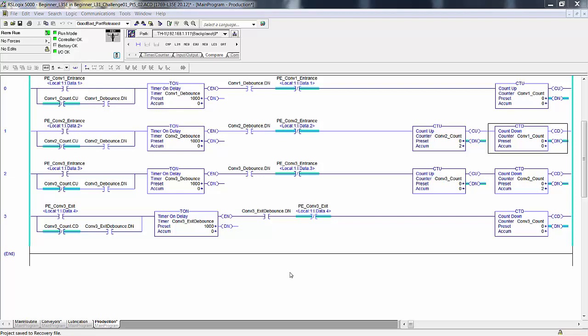It is not a good idea to start writing the controller program until this phase is completely finished, including and especially the documentation electrical drawing set. Now, somewhere in between here and the finished electrical drawing set with RS-Logix 5000, you can start writing the program. Once the process has been well defined, even though the electrical prints are not done that have I/O assignments, you can start with RS-Logix 5000 because of the advent of concurrent engineering.